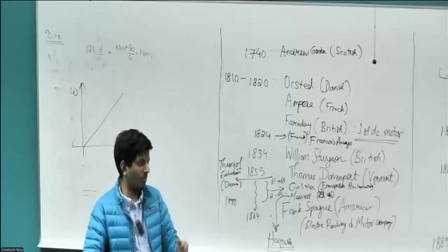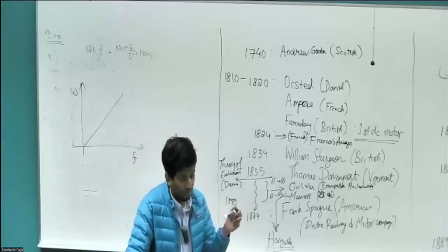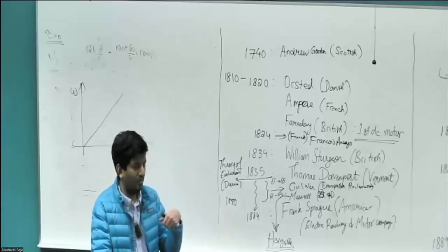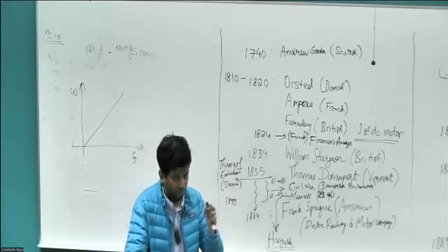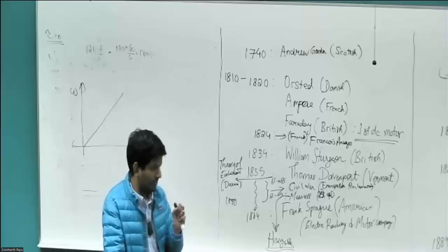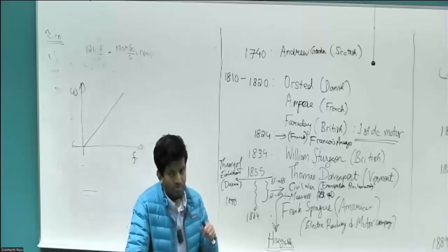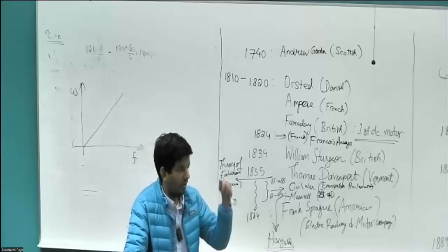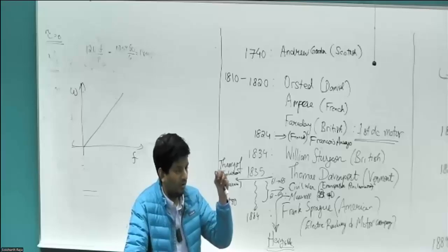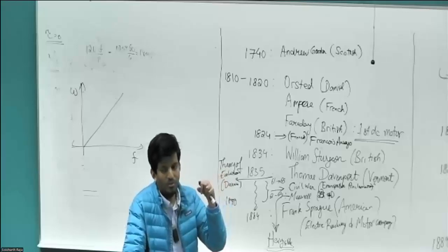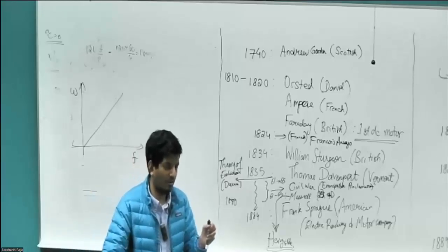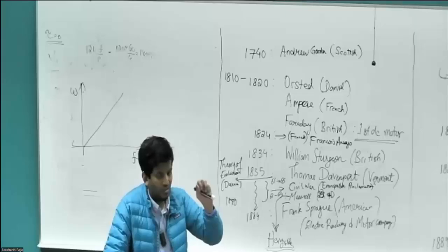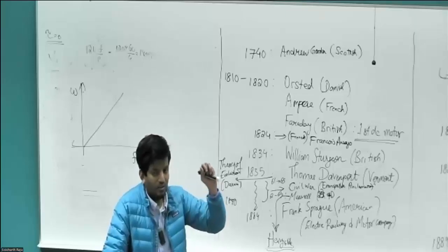And the second problem is when the rotor is spinning, there is something called a back EMF that's induced on the stator winding, which then limits the amount of current that flows into the stator winding. This is extremely critical. When the rotor comes to a stop, the back EMF goes to 0. So from the grid's viewpoint, what it looks like is basically a pure resistor with some inductance, which typically, let's assume, is very low for a permanent magnet synchronous motor. So it's some resistance connected across, very tiny resistance connected across a very large voltage.